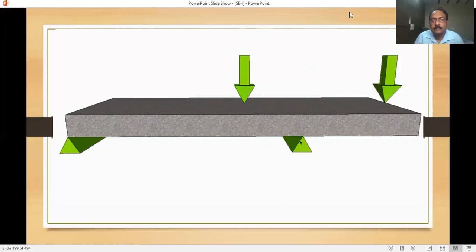In this instance, such as a cantilever, we've got a load down in the middle, and again we're going to have the self-weight of the slab plus anything else we're going to put out here on this end of the slab, causing a load out here. So there's actually going to be a bend over that support and a bend in here as well.